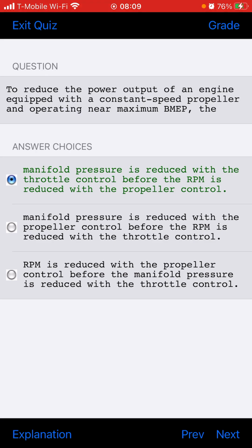When the control is released, it will spring back a few degrees. Direct mechanical push-pull carburetor heat control linkages should normally be adjusted so that the stop located on the diverter will be contacted before the stop at the control lever is reached in both hot and cold position.